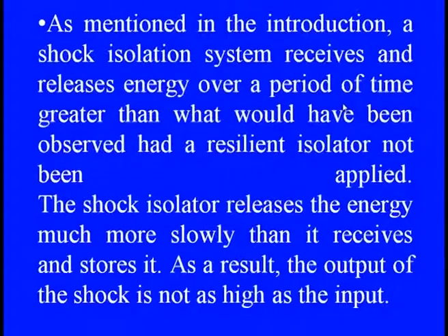So we can say that the shock isolation system receives and releases energy over a period of time which is longer than what we have generally seen for the resilient isolator. The shock isolator releases the energy at a very slow rate after it receives and stores it. The output of the shock is not as high as the input. Sometimes we see the overdamping phenomenon, in which the system comes to the steady state over a very long period, because the energy release is so slow.